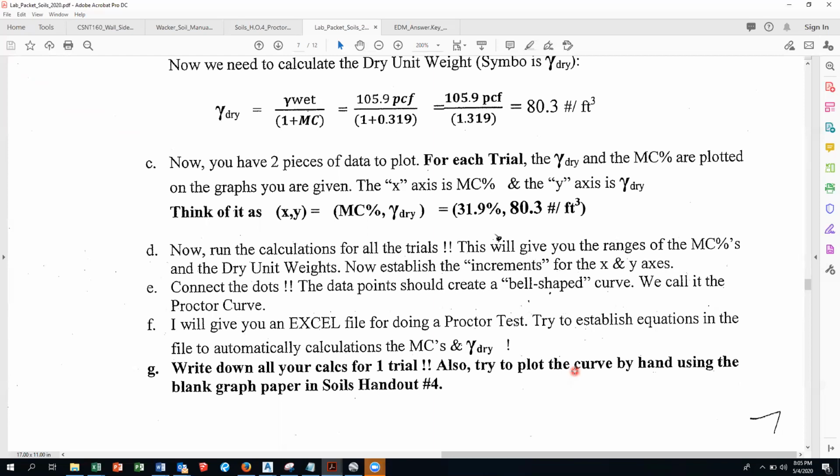Then we're going to get some specifications, and we're going to highlight those and show you where it's written that a soil is satisfactory or unsatisfactory, or it has to meet 95% of the maximum dry density from the proctor, or 98%. So we'll get you acclimated to the specifications as well. And then we'll run the test when you get back. It's a lot of fun. Like I said, that and pizza, it'll be good.